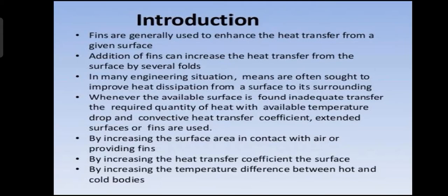Whenever the available surface is found inadequate to transfer the required quantity of heat with the available temperature drop and convective heat transfer coefficient, extended surfaces or fins are used. By increasing the surface area in contact with air or providing fins, by increasing the heat transfer coefficient of the surface, or by increasing the temperature difference between hot and cold bodies, we can observe that fins are generally used to enhance heat transfer from a given surface. They can increase the heat transfer from the surface by several folds.